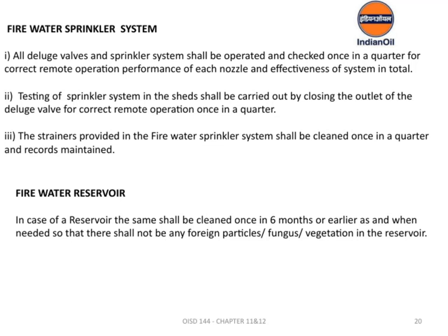Now, let's discuss the requirements for the fire water reservoir as per OISD 144, Chapters 11 and 12. It's important to note that the reservoir must be cleaned at least once every 6 months, or even earlier if needed. This helps prevent the buildup of foreign particles, fungi, or vegetation that could compromise the water quality or system functionality. Regular cleaning ensures the reservoir remains in optimal condition for fire safety.